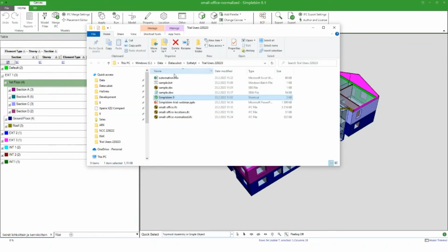And when you set up the automation, all I did was double click on this batch file, which ran this script, which imported this model, which applied this template, which exported this new IFC file. Just running a batch file, and bing, there it is.